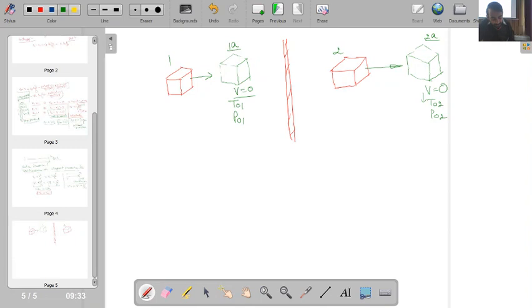Now I am writing the entropy change S2a minus S1a. So S2a minus S1a will become Cp times ln of T naught 2 divided by T naught 1 minus R ln of P naught 2 divided by P naught 1. So this is what we will get over here. Now, the process from 1 to 1a is isentropic. Similarly, the process from 2 to 2a is isentropic. So for this process I can say that S2a will be equal to S2.